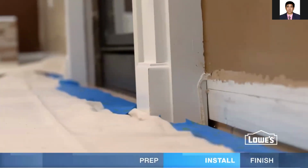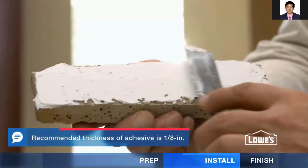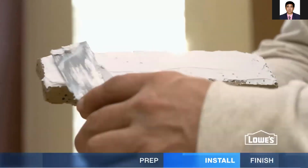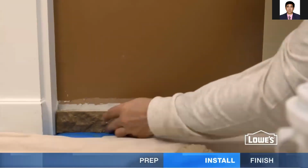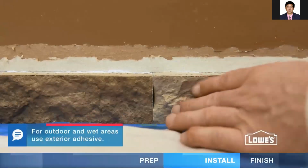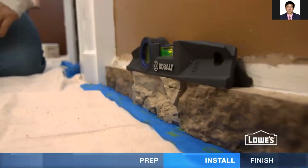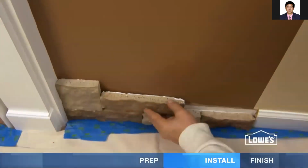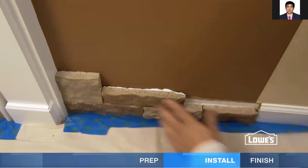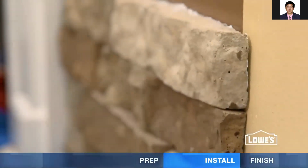Start the install at the bottom corner. With a putty knife, apply a thick layer of the adhesive to the back of the stone, sort of like icing a cupcake, and press it onto the wall. Do the same for the next piece, keeping the joints tight, and finish row 1. Make sure everything's level. Then start the second row. Remember to stagger the joints and keep them tight. At the row ends, use a natural stone edge for a finished look.